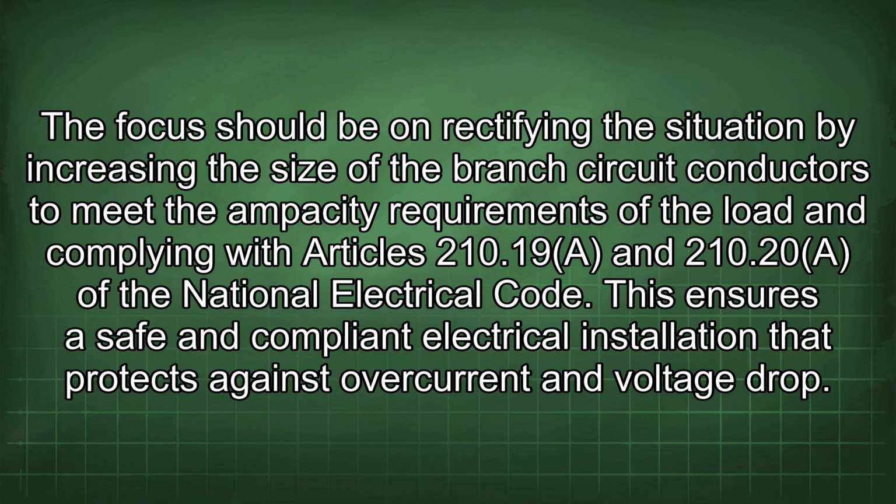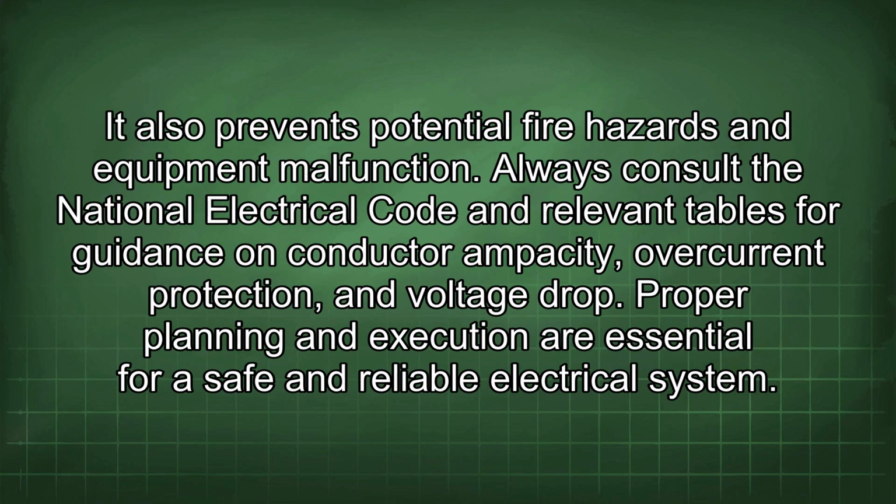The focus should be on rectifying the situation by increasing the size of the branch circuit conductors to meet the ampacity requirements of the load and complying with Articles 210.19 and 210.20 of the National Electrical Code. This ensures a safe and compliant electrical installation that protects against overcurrent and voltage drop. It also prevents potential fire hazards and equipment malfunction.